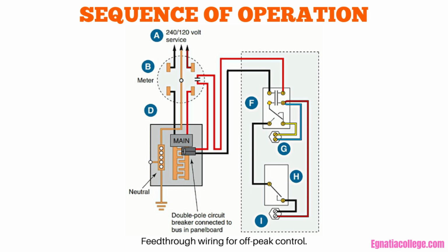The heat insulating jacket around the water heater is designed to keep the heat loss to a minimum. Thus, it takes many hours for the water to cool only a few degrees. Most of the time, the bottom heating element will keep the water at the desired temperature. If a large amount of hot water is used, the top element comes on, resulting in fast recovery of the water in the upper portion of the tank, which is where the hot water is drawn from.